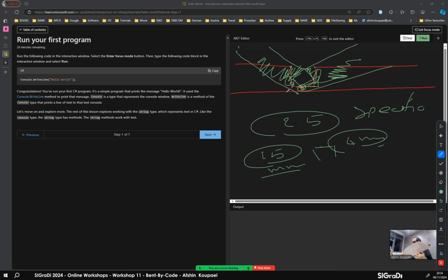The axis is different. Here, the axis is different. And then because of that, the shape actually changes, right? So there was another problem here, that when you are bending this, you have only a very thin layer of plywood here, which is very fragile. So when you bend it, if you fix it, it cannot tolerate any forces, and it needed to strengthen.